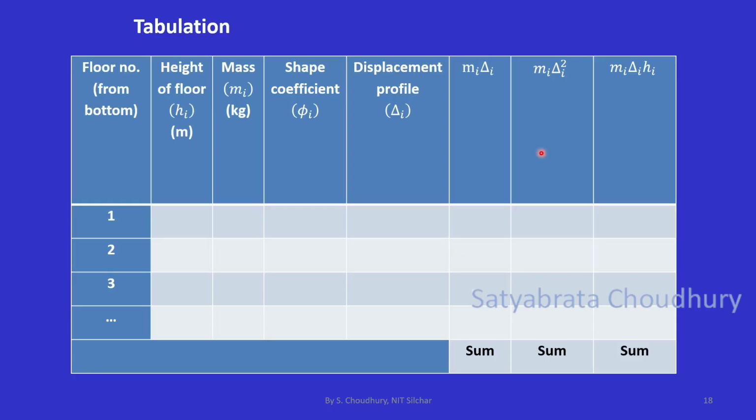Those you applied, and in that process, Priestley and Pettinga, in their paper, what they've done, they have considered the percentage steel in the beam as varying from say 2% in each face, and the percentage steel in column ranging from 3% to 4%. This variation of the percentage steel will enable you to decide the size of the column and size of the